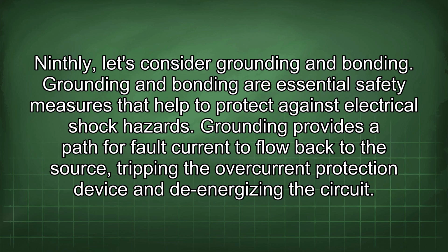Ninthly, let's consider grounding and bonding. Grounding and bonding are essential safety measures that help to protect against electrical shock hazards. Grounding provides a path for fault current to flow back to the source, tripping the overcurrent protection device and de-energizing the circuit.